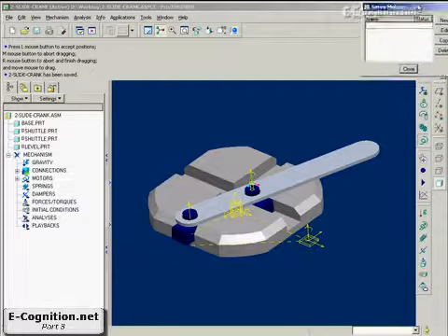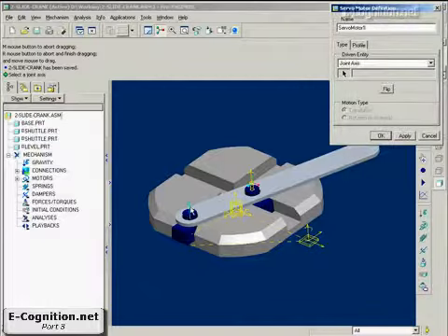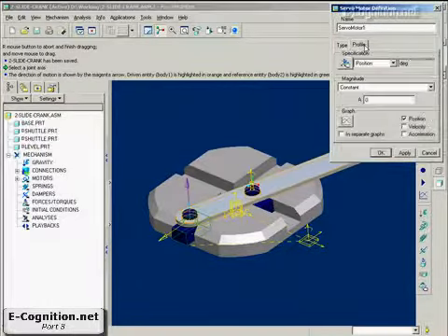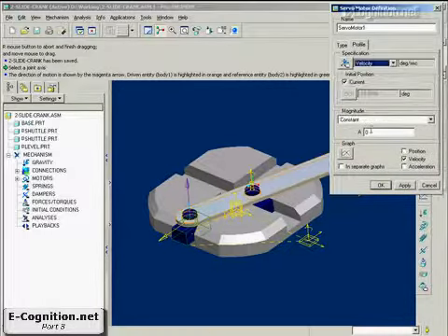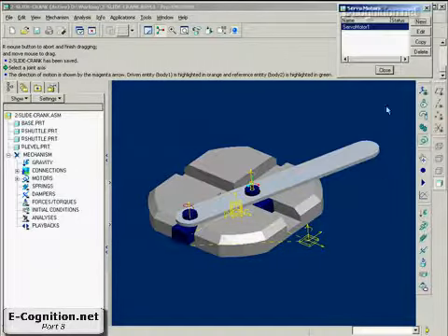So we'll make a new servo motor, and the joint axis we're going to put it on is here, and then the profile might be a velocity of a constant angular velocity. So if we want it to go, say, 360 degrees in 10 seconds, we'd want 36 degrees in 1 second. Alright, so we'll call that OK.